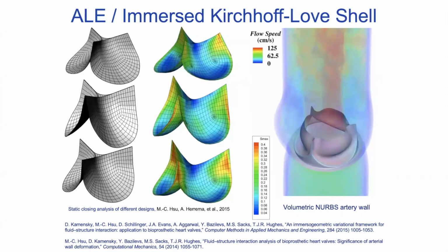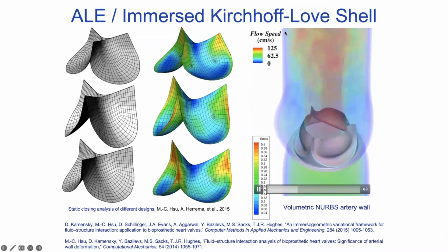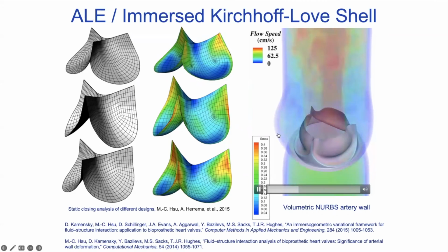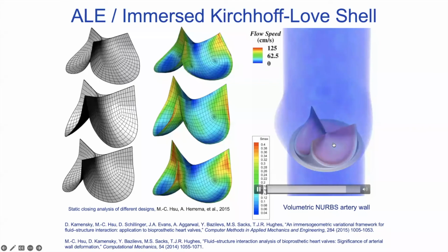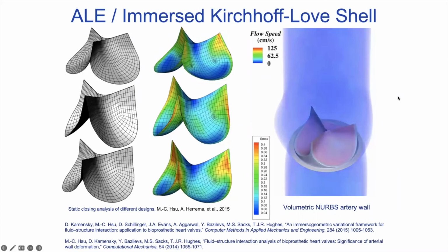And the technology is quite complicated here. It's a combination of moving mesh technology, a variational multi-scale Navier-Stokes solver, a hyperelastic generalization of the Neo-Hookean model for the wall. And then you have these finite deformation leaflets modeled with Kirchhoff-Love smooth shell theory. And that's all going on. That's moving with respect to the background moving mesh of the fluid.